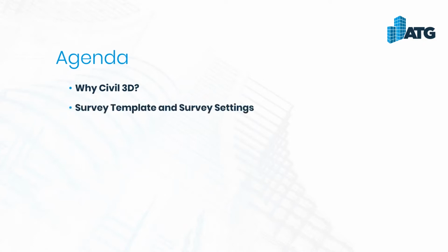Some of the things that I'm going to go over are how our survey template and our survey settings work, the places where we want to look. Obviously 30 minutes is not going to be an exhaustive training on all of this, but I'll show you all the big pieces and where they live. We're going to be looking at our survey description key set. This is going to manage our points. So when we import the points, if the parameters from our point file match the parameters of our Civil 3D template, good things will happen.